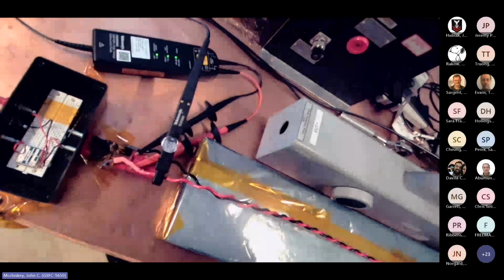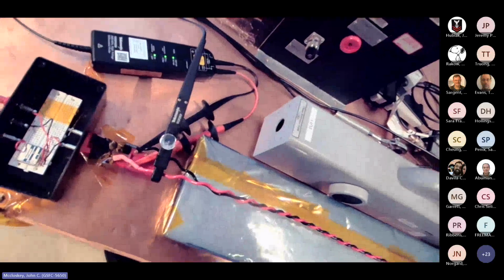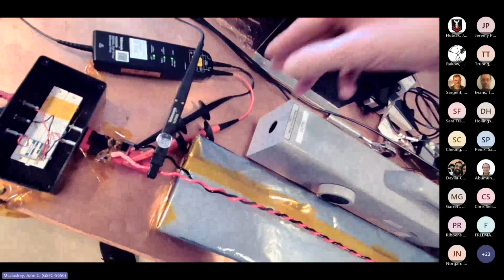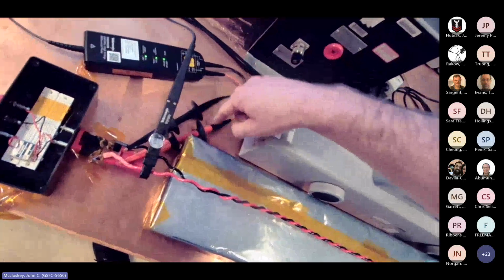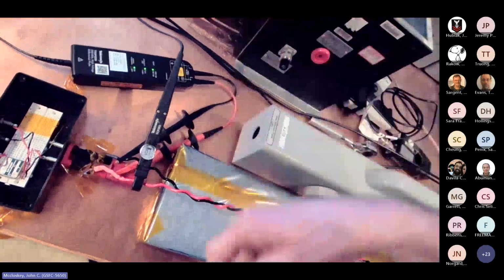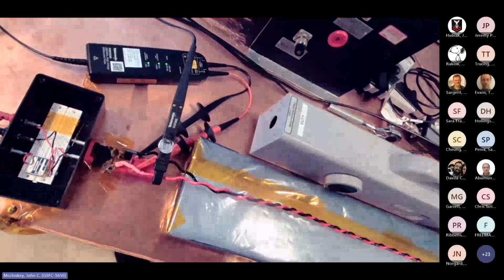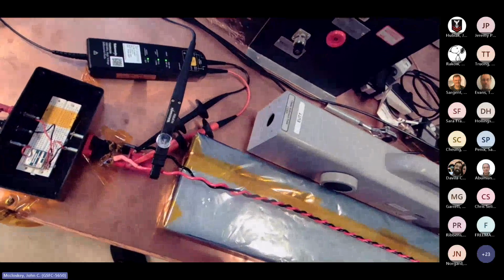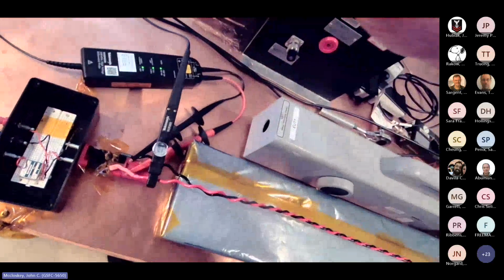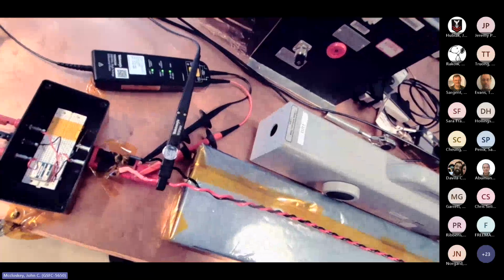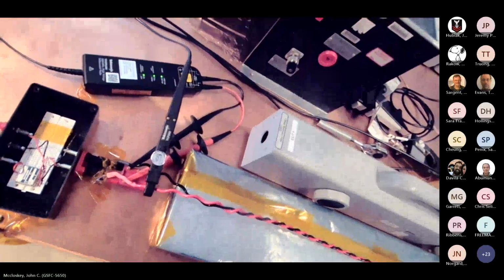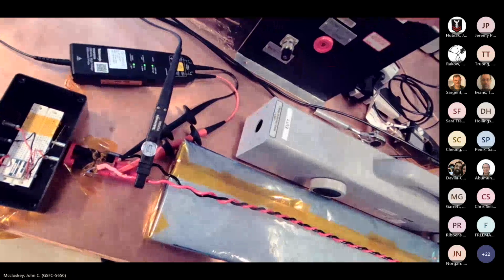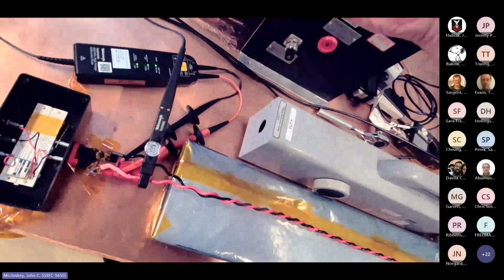A lot of times it's just fine, but if you use a differential probe where both leads present a high impedance with respect to facility ground, you generally get more reliable results, and whatever your connection to facility ground might be doing to you is removed from the picture. So another bit of test and measurement stuff that I like to pass along.